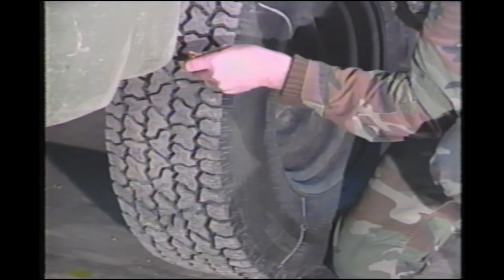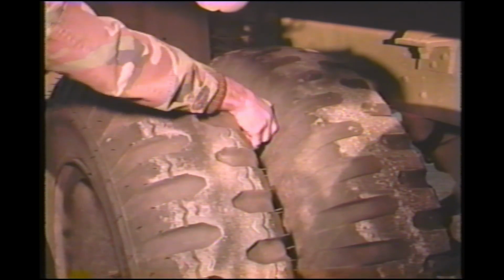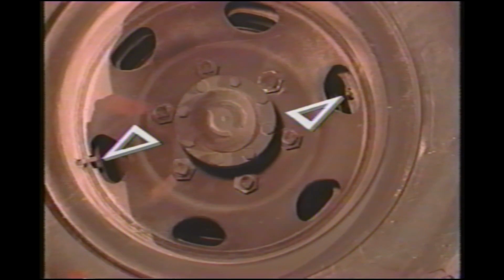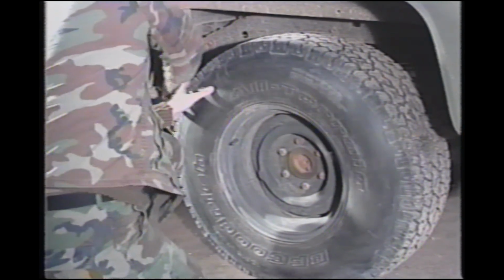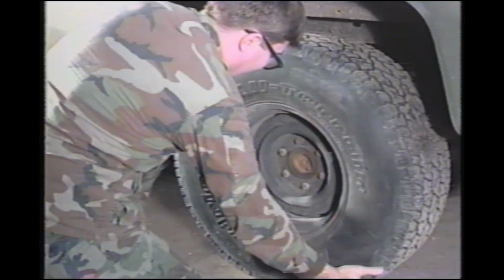Perform the inspection exactly as before. Scrape rocks from the tread grooves and look for signs of damage. For vehicles with dual tires, remove any rocks or debris from between them. Also check to ensure that they are mounted so the stems are 180 degrees apart. Inspect all tires with the same scrutiny. Develop thorough inspection habits. Set a routine by following the same sequence each time.